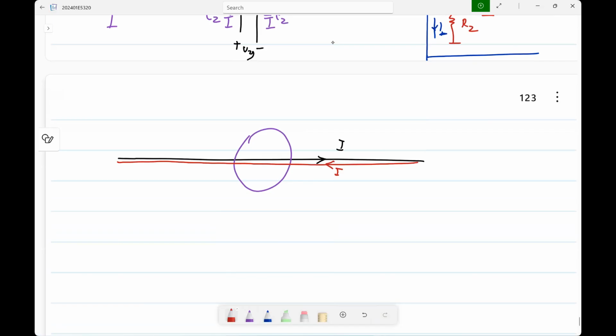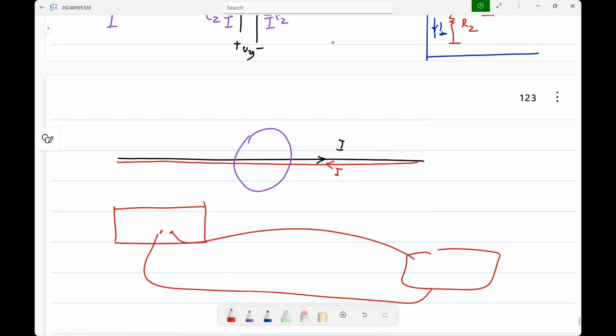I don't know if I have that old slide here. I have something to show. So anywhere you make connections, things have to be like this. Let's say you have power supply wires and you have something like that. This is not a good thing. The way to connect wires would be to take these two and then maybe twist them together so that they don't enclose a large area. This way their magnetic fields also will get cancelled out.